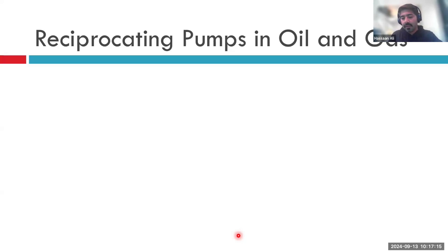However, with the quest to move towards zero net carbon emissions, a lot of operators are moving towards providing electrical power on site. If that is not possible, we have gensets on sites that can effectively make that lease self-contained or self-sufficient. So essentially what we are seeing in the market coming up now is that the reciprocating pumps, rather than being driven by diesel engines or natural gas engines, are being driven by electrical motors. That is new and upcoming. It is still a very new technology, but people are adapting to it more.